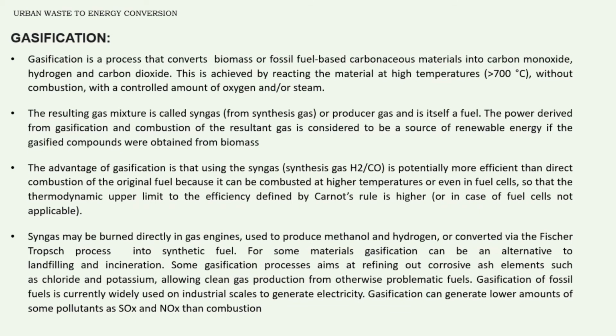The second type of energy conversion from waste is gasification. It is a process that converts biomass or fossil fuel based carbonaceous materials into carbon monoxide, hydrogen, and carbon dioxide. This is achieved by reacting the material at high temperature, more than 700 degrees Celsius, without combustion, with a controlled amount of oxygen or steam.